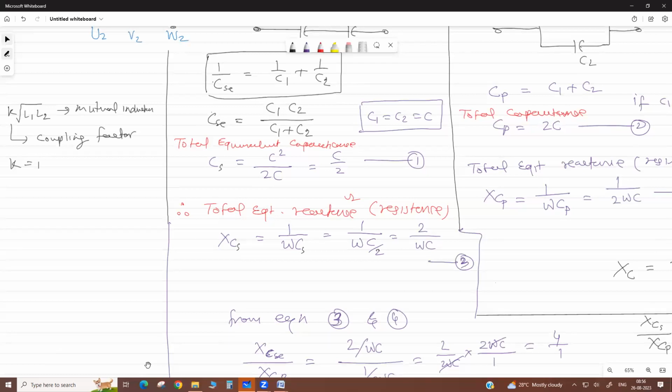Actually, it is an application of series and parallel resonance. Series resonance is used where you need minimum impedance, so it is low impedance for the tuning frequency. For the incoming frequency where we require low impedance, that circuit is used. But parallel resonance, is it separating the wanted frequency or unwanted frequency? It separates the wanted frequency.